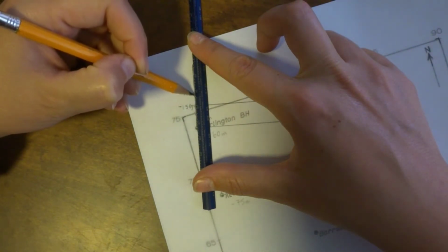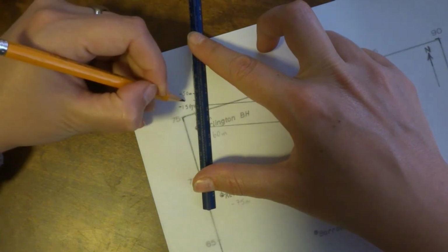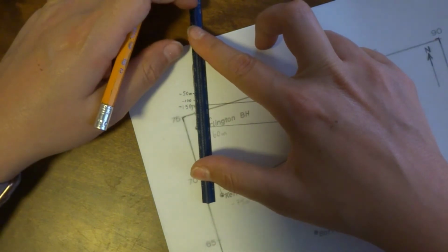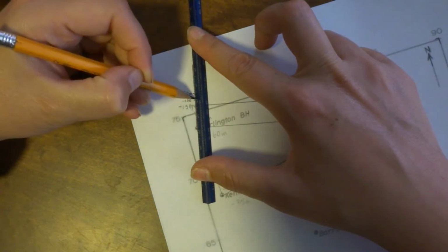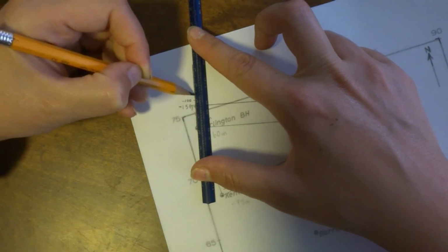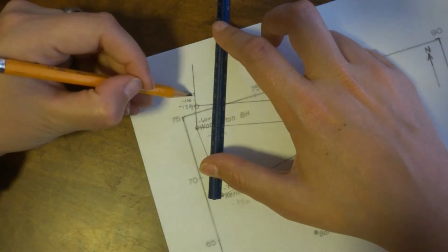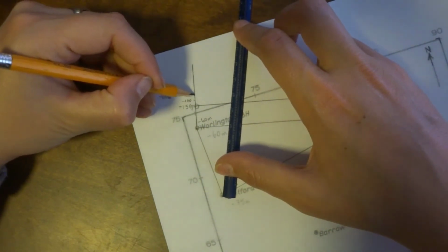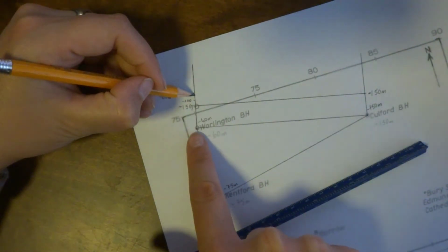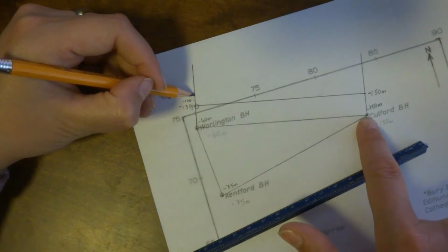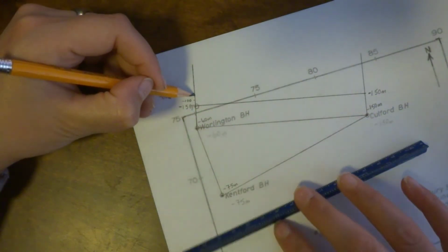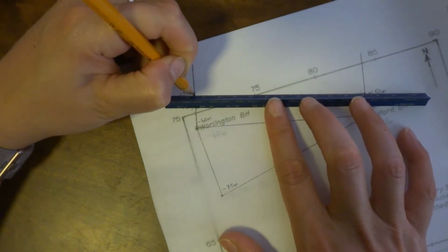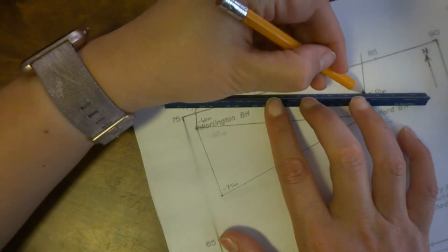So we can say 0.41 centimeters is minus 100 meters. And some further interpolation to find minus 60 will be less than a millimeter. And we can call that our minus 60 meters. Once we have that 60 meters here, we know that the topography extends from this point to that point between minus 60 to minus 150. So we do that, we draw that connection on our little cross section with a straight line.